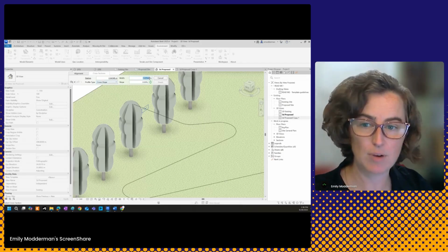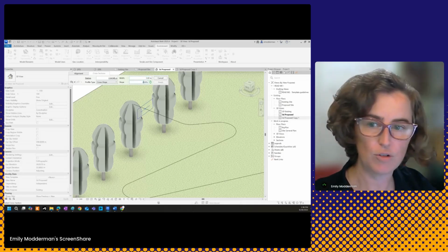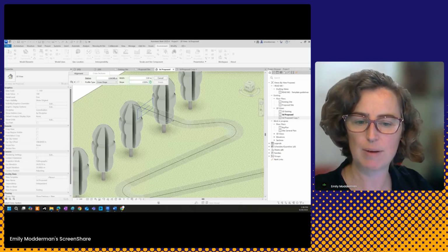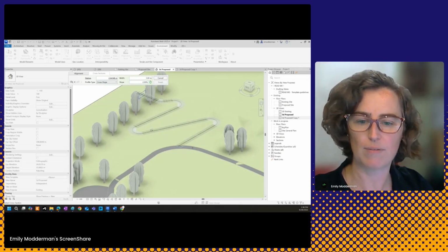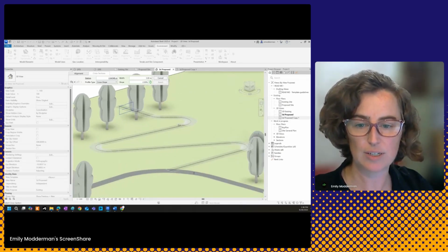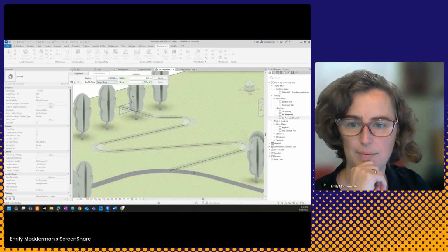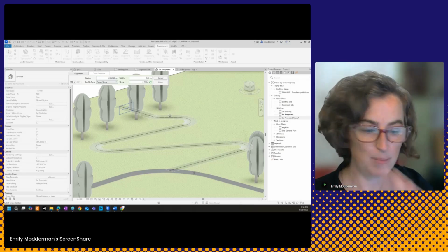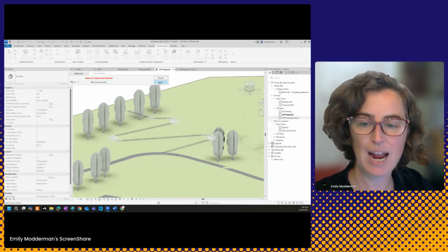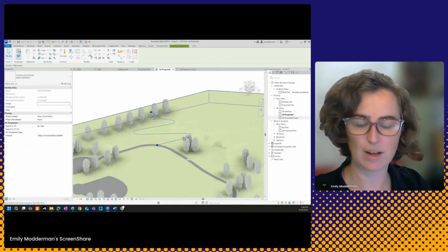In this case, I am not going to use a profile. I'm simply going to say I want a 3-meter wide pathway with a 2% cross slope. And when I hit this little regenerate button, it's going to build me what they call a reference surface. So this is just something in the background that represents my surface and provides that information about the cross slope or the profile. Now, that all went fairly smoothly, so I can hit escape a couple of times and finish that. And it gives me a little floating alignment point.